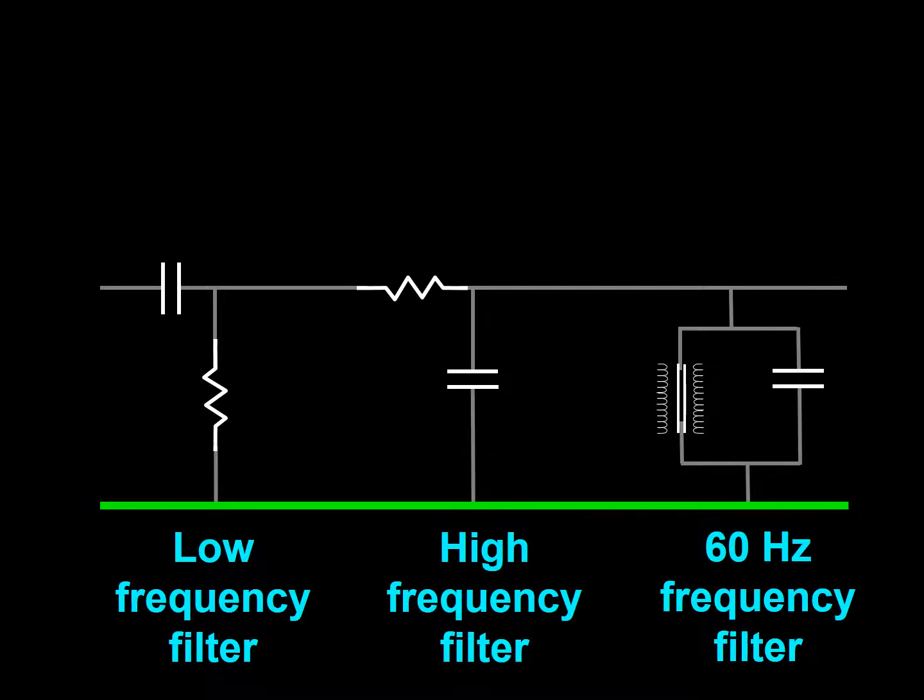Currently, the newer EEG machines, so-called digital EEG machines, only use modern, not classical, analog high-frequency filters. Yet, judging by the frequency of the questions in the neurophysiological boards exam about classical analog filters, you would think that they are still in high use. So, to keep up with the high numbers of questions about classical analog filters in all exams, I will discuss the three classical analog filters thoroughly.